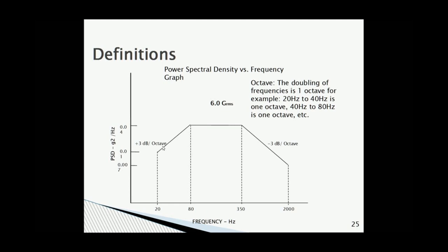Now, one more thing too is when you control a vibration test, you are controlling at only certain frequency points. You are not controlling at every single point, even though every single frequency point here is occurring in your random vibration test. You're only controlling to certain points. Now, the more points you are controlling to, the higher your resolution or the greater your control is. So lines of resolution is the number of frequency control points that you are controlling to for a random vibration test.